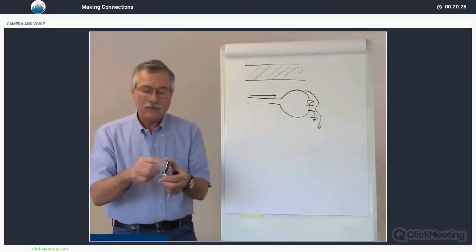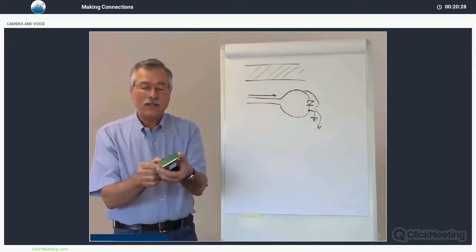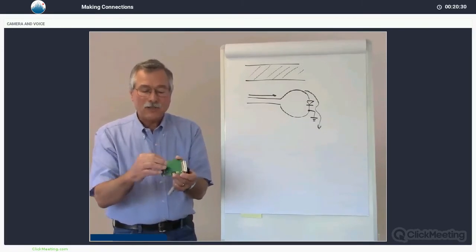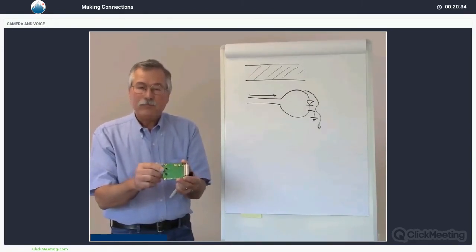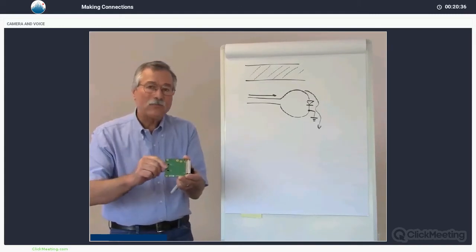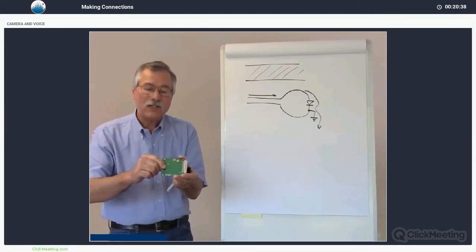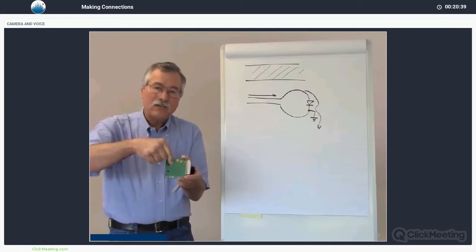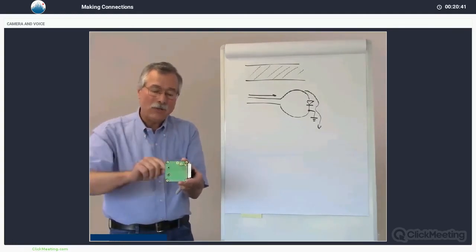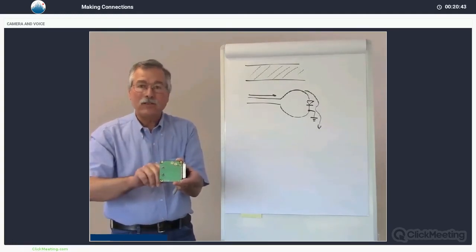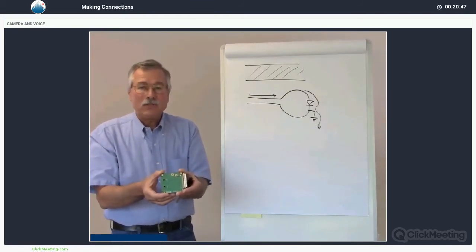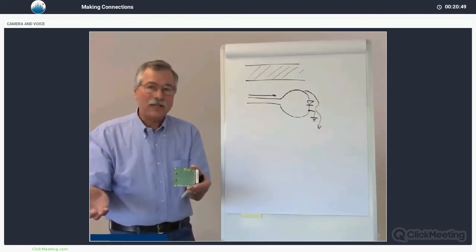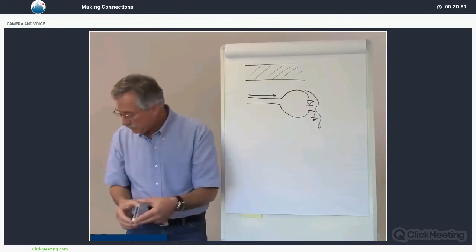Here is a board that has a DE37 on one side, and it's got a ground plane on one side and a power plane on the other side. We can put the laser diode and straddle the board if you wish, soldering one lead to each side. You can put the laser diode in on right angles if you want to by putting a hole in the board and soldering one lead to one side and one to the other. It's an easy way to interface the package of the laser diode to the strip line.